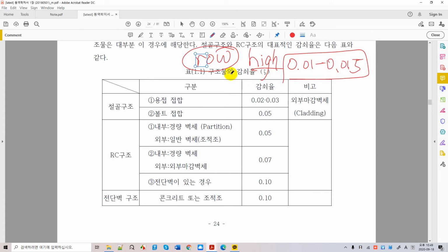All right, but low-rise buildings are okay. You have a rather large damping. It depends on materials, from 5% to maybe 10%. That's okay, and it's enough to stop your building in very short time. But something is different when you think of a high-rise building. High-rise building is very hard to stop because your damping is very small.